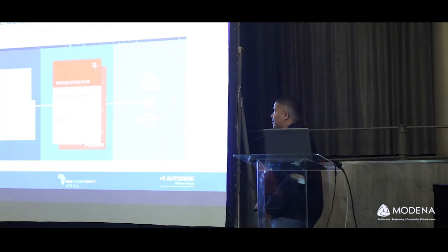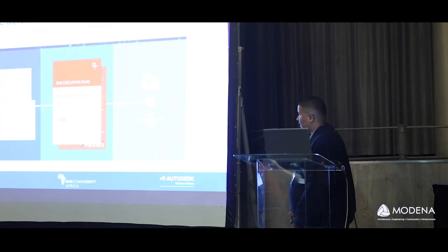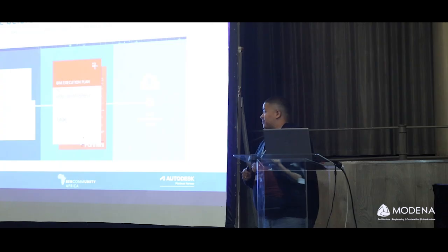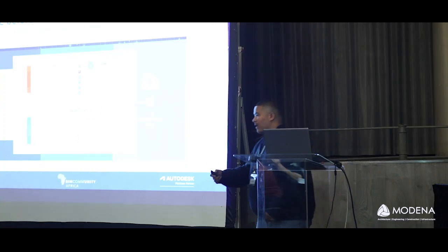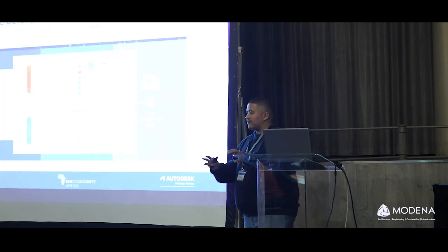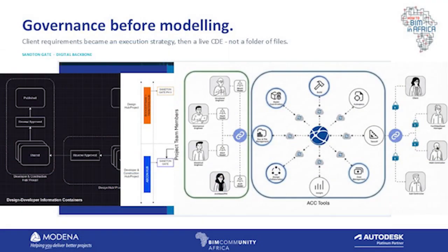We then responded back with the BIM execution plan. And this is basically, as you guys know, with BIM execution plan, this just means it's basically a rule book on how the project is going to be delivered. We then responded to, okay, how we have 2 different hubs. Great, fantastic. 2 CDEs, but how do we share or exchange information? We then used the bridge toolset. So when information is pre-checked before it hits the client.